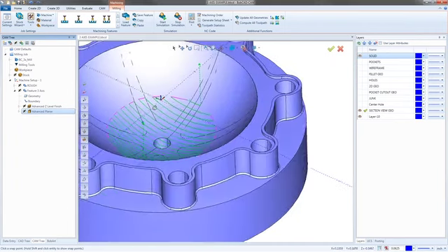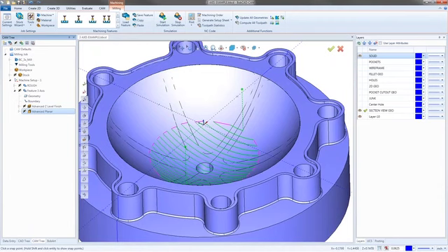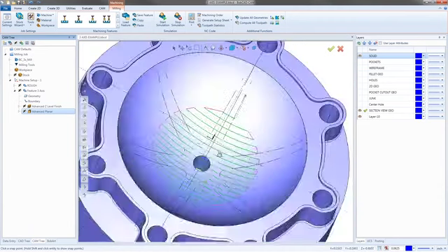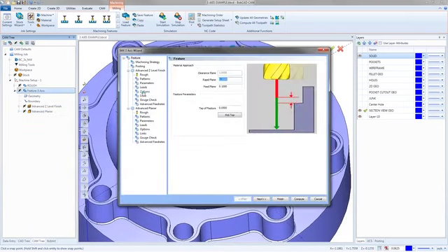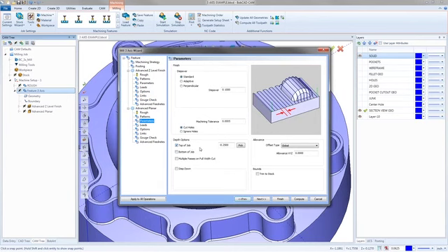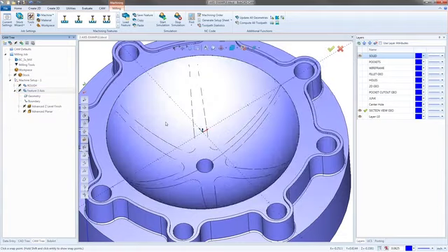There it is. Now you can see. So that's a good way of getting rid of this area, this top section, if it's not needed. Just change the top of feature, top of job under the parameter. So you change the top of job to a negative value and let it cut from that value down. I didn't need anything above it, so there's no reason to have it there. Okay, I thought I was crashing.